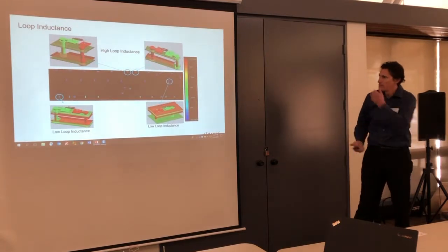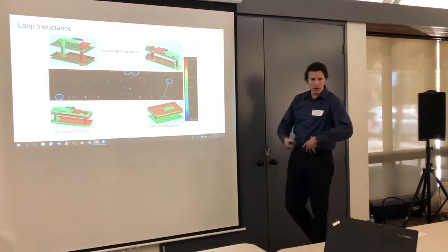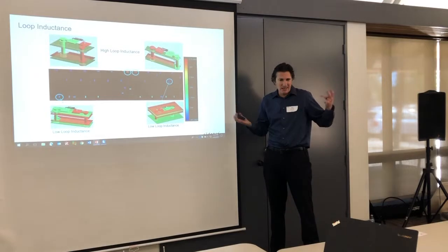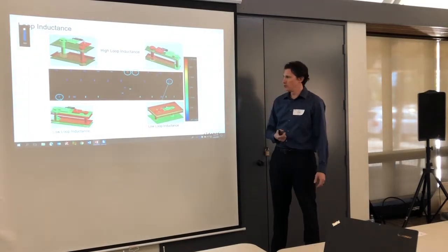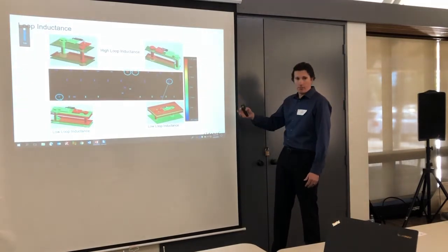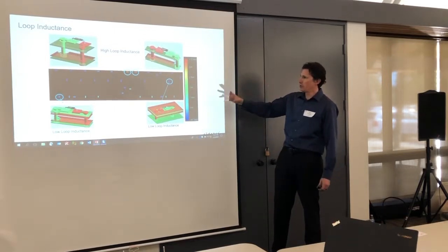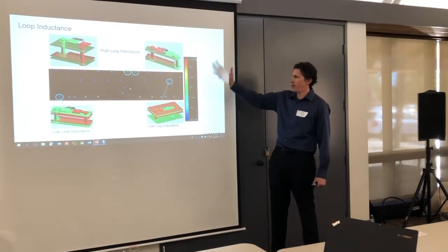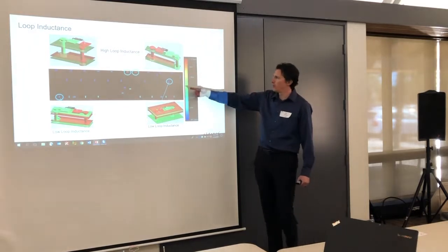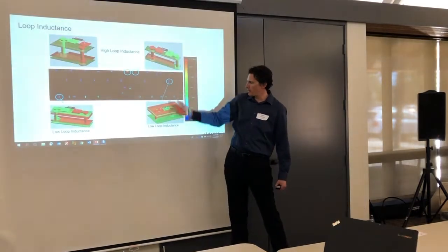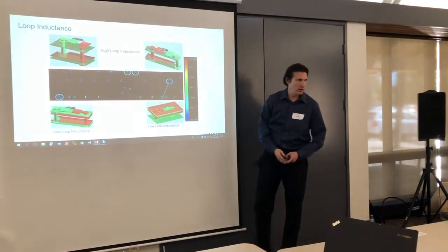Looked at another way, you may have a design, and every design I see has at least 500 of them, right? So I would always recommend, if you have the opportunity, analyze your design afterwards and see if you can have it tell you where you have capacitors that have high loop inductance, based upon the way they're connected to many, many layers down versus the nearest power and ground plane layer.